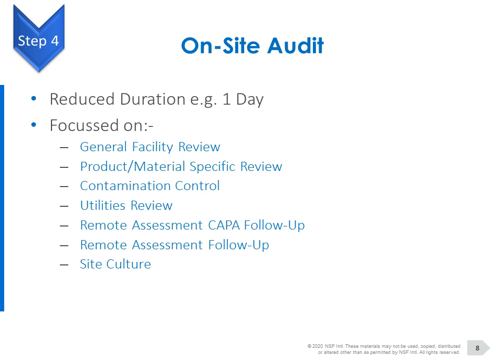If we deem that the facility is suitable, then we could go for an interim approval, but there may be some mitigation that we want to introduce. So we may decide that as we haven't actually been to the facility, we may want to increase the level of scrutiny or oversight on materials that we're receiving via maybe additional sampling or testing, or applying additional QA oversight to the facility, where we may want to review part or total batch documentation.